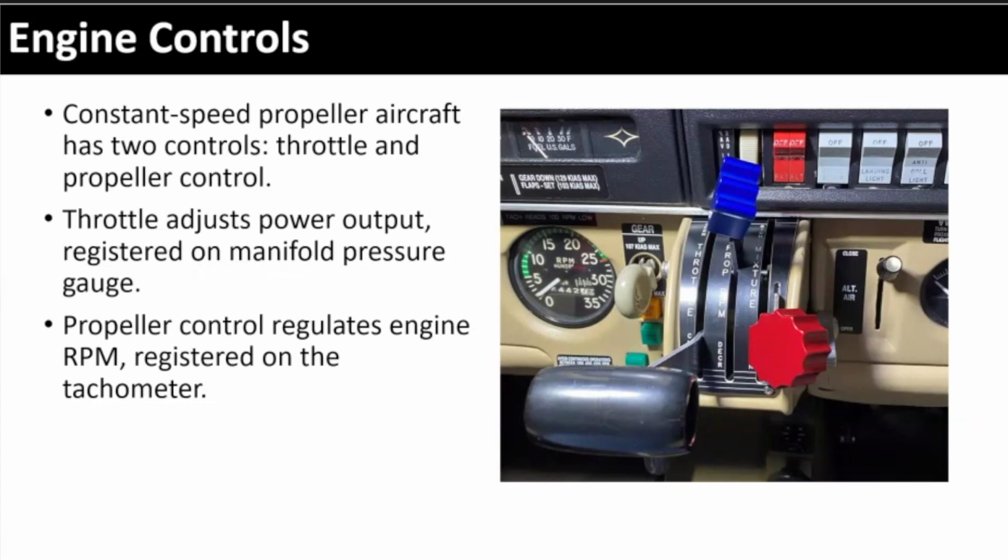So with the constant speed, when you decrease the RPM, you're adding more load to the engine, which would decrease the RPM gauge. Right? So you're kind of playing this game between the throttle and the constant speed. No. When they're independent. Yep. Right? So when you set the prop speed, the governor and the system is going to maintain whatever you set that at.